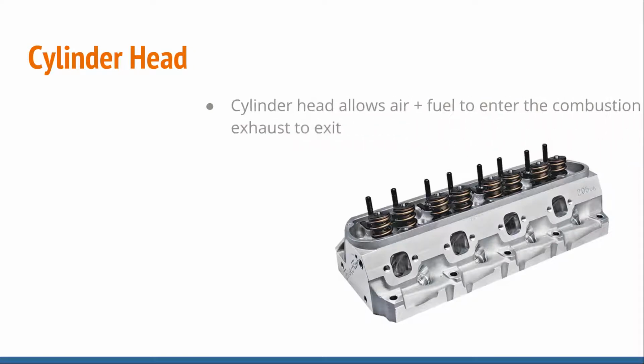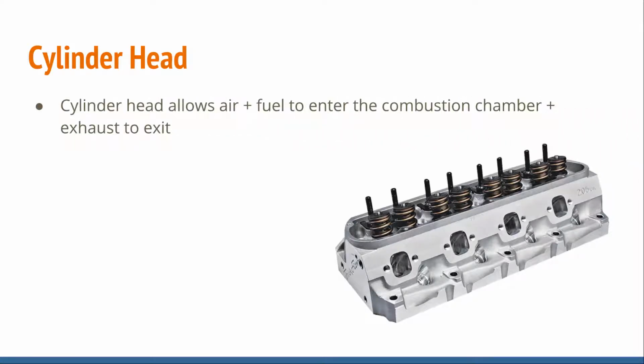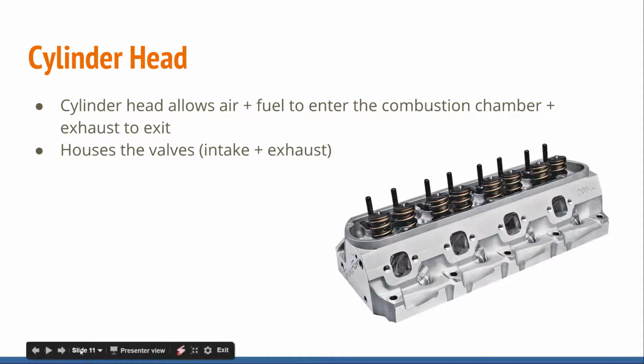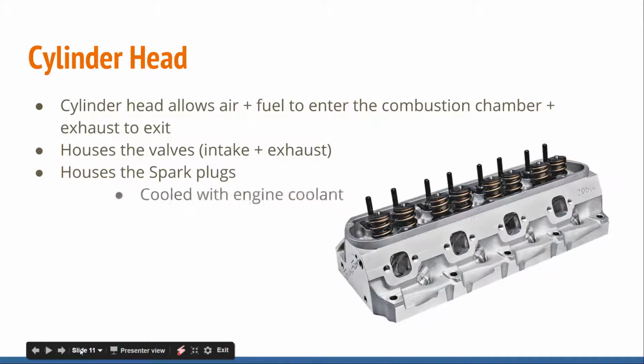Cylinder head. So the cylinder head allows air and fuel to enter the combustion chamber and exhaust to exit. Houses the valves, the intake and the exhaust valves. You can see right here. Also houses the spark plugs, cooled with engine coolant. Every cylinder head you're going to run into has coolant running through it, and it goes right through the cylinder head through different coolant passages, keeps it cool. It also helps it warm up on a cold engine.